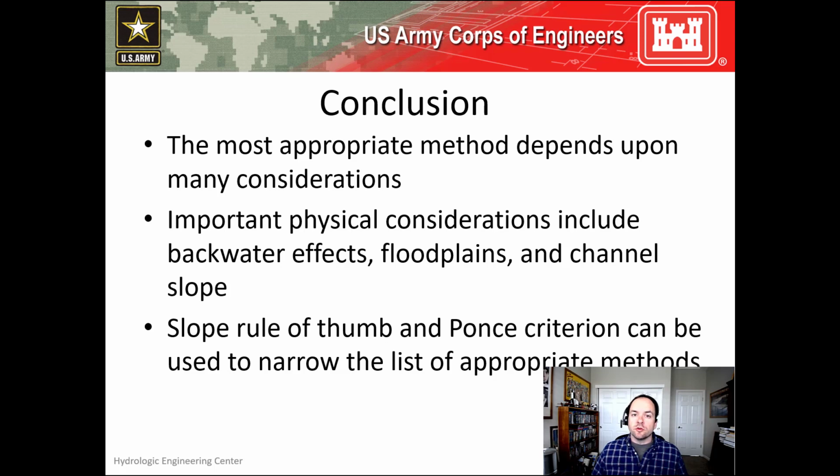Now in review, the most appropriate routing method for a specific situation depends upon many considerations like study constraints, data availability, output requirements, and physical considerations. Important physical components of the system in question include backwater effects, floodplains, and channel slope. Feel free to use the rules of thumb and tables presented near the end of this video to quickly identify